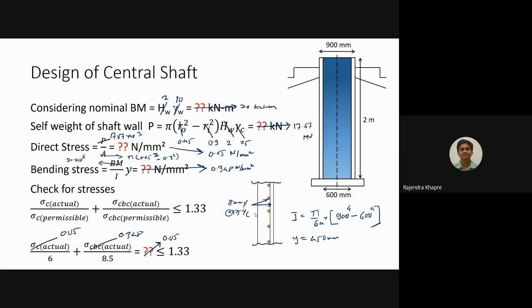Here you need to remember one thing. We have to provide the reinforcement on both the sides if the thickness is greater. This we have already seen in the design of GSR, especially the cylindrical wall. So the same rules are applicable over here, but since the thickness is less, we can provide the AST in this particular fashion. And please do mention the thickness also. Here the thickness is 150 mm. So please mention that one also.